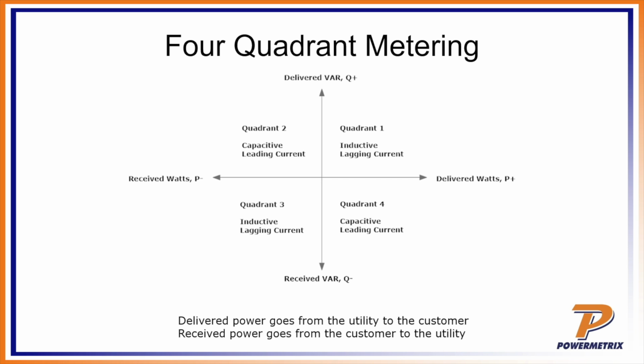If I take an oscilloscope and look at both the voltage and the current waveform, for a purely resistive load, those two are going to be on top of each other. That's good in that it gives you a power factor of unity and purely watts coming out of that. As we add inductance, the current starts to lag behind, the sine wave starts to shift later in time, and so that phase angle opens up. The phase angle is simply the time difference between the voltage and the current.